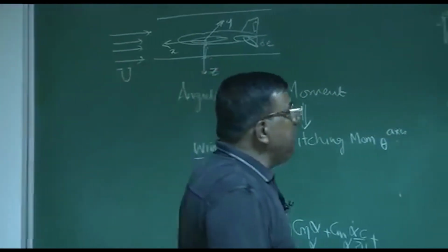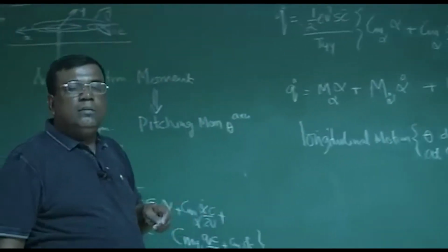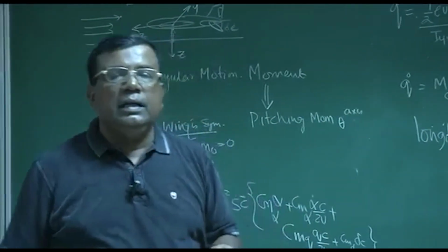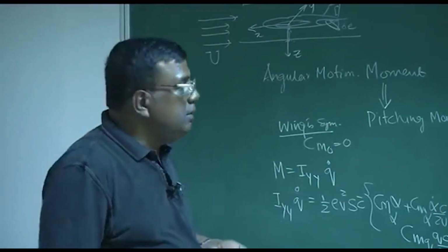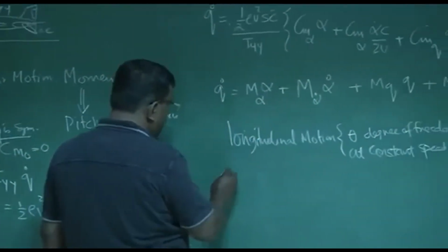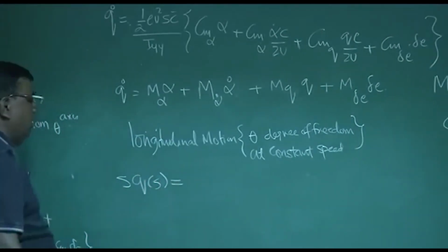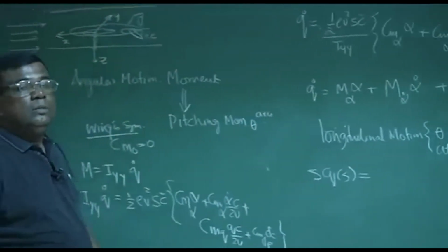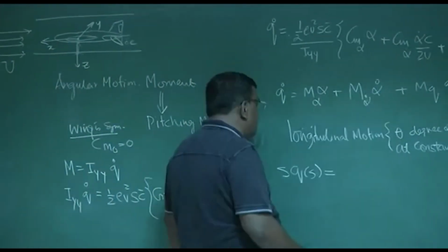But there is a definite meaning of why we are looking for pure pitch. You will see that if this plunging motion is not really much, then I get a lot of information from this simple equation, in terms of the natural frequency of that mode as well as the damping ratio. And that is why we are doing this. So now I take the Laplace transform, with initial condition 0, and you know all these things very well. We are talking about a linear system, and it doesn't depend upon the initial condition, so putting the initial condition to 0 doesn't change anything. We have discussed this in the last few lectures.